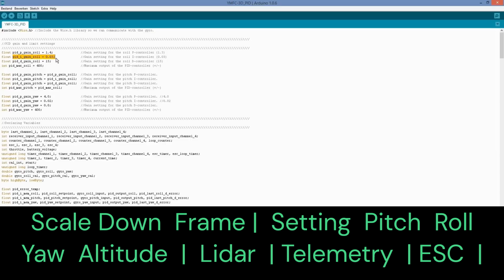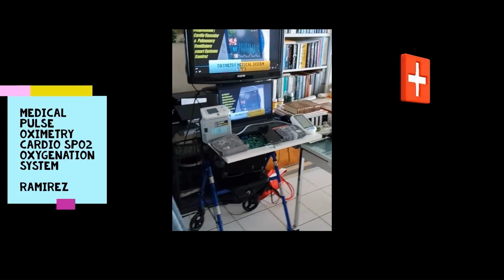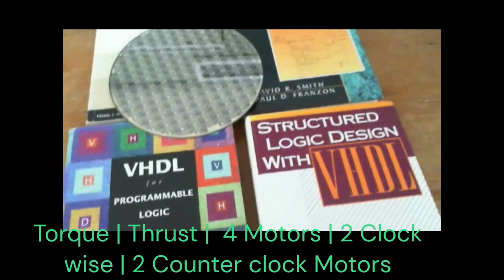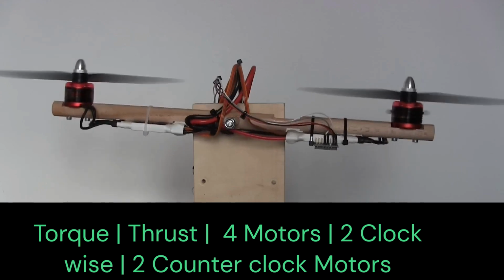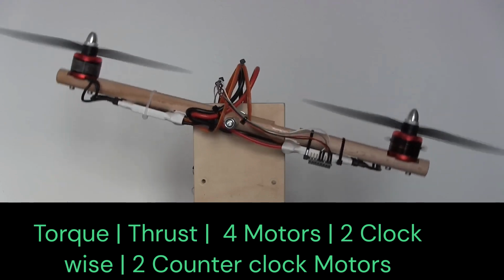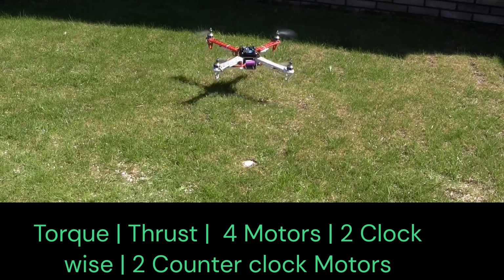These include focusing on how to assemble all the different components of the current smart drone. Also paying close attention to the thrust of the motor after mounting the motor on the frame. This is extremely important. It will tell you whether your drone will float in the air or fall down,